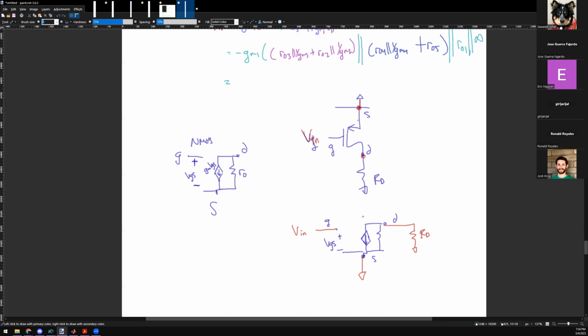And this is also a PMOS. Even though it's drawn like this, don't actually draw the gate, drain, and source in that upside down configuration. Draw the same model and then go back to the original drawing and pick up the connections. Draw all the connections to the gate, all the connections to the drain, all the connections to the source. Okay, that makes sense. Thank you.